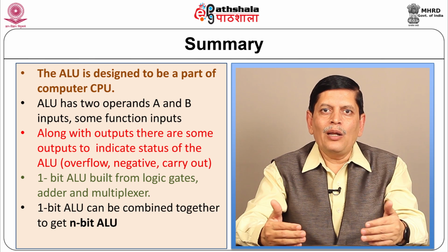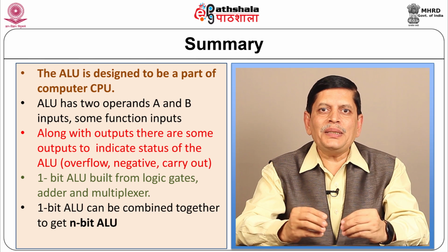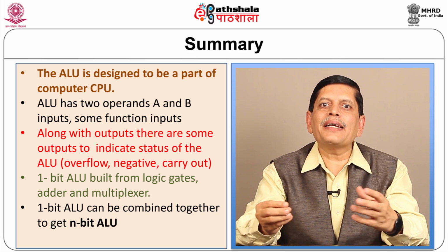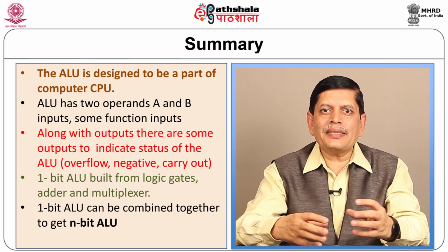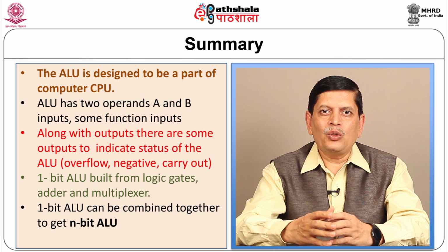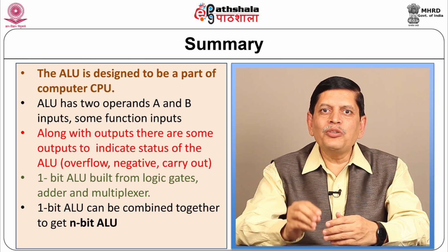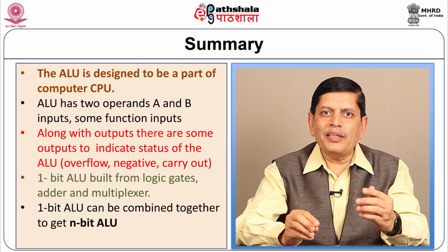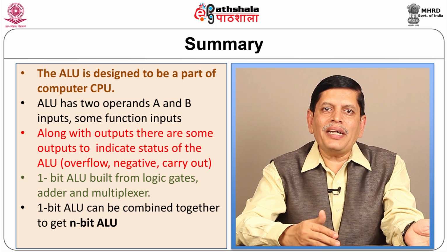Now, to implement the logic unit first, we have identified 4 basic functions AND, OR, NOT and XOR, and these basic logic gates are connected through a simple 4 to 1 multiplexer to get the desired operation. The function select lines allow the designer to select one out of 4 operations.